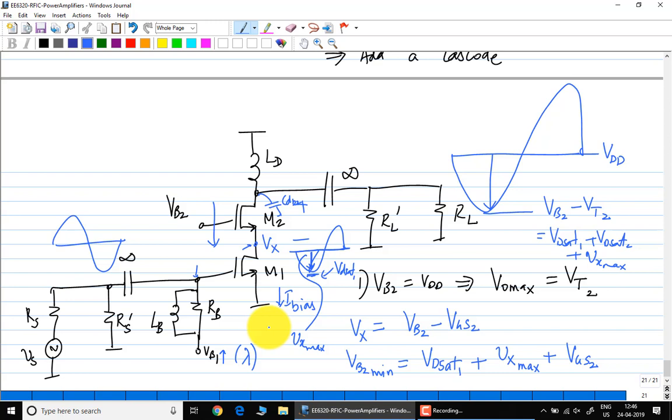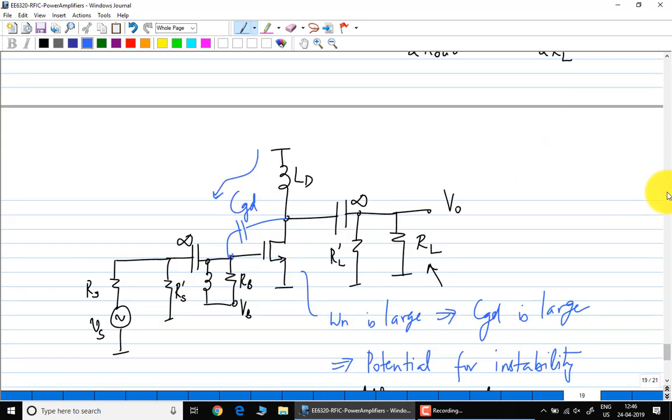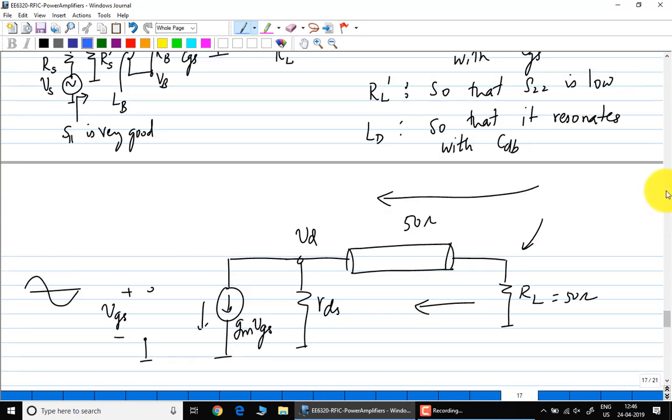That's pretty much what you're getting at this. What is plus 5 dBm? Plus 4 is about 4 milliwatts. Plus 5 is about 6 or 7 milliwatts, something like that. Yeah, that's pretty much what you're able to get out of CMOS at these power supplies. It's clear that you can't easily get several tens of milliwatts or hundreds of milliwatts of power. Now it is possible to get hundreds of milliwatts if you match down to a few ohms of impedance and so on. If you really need to cut down costs, you would do it because the cost of gallium nitride, gallium arsenide is much higher at the end of the day.